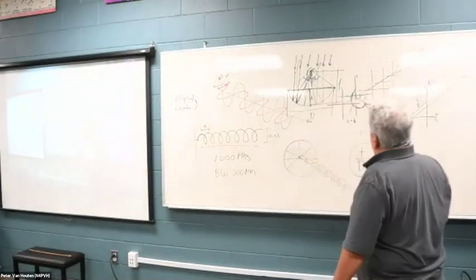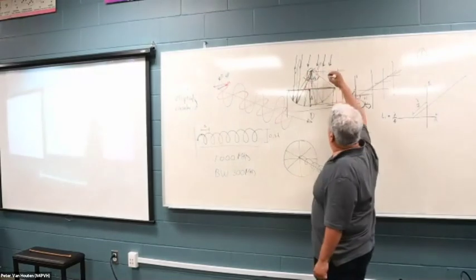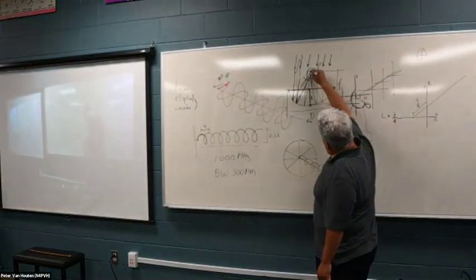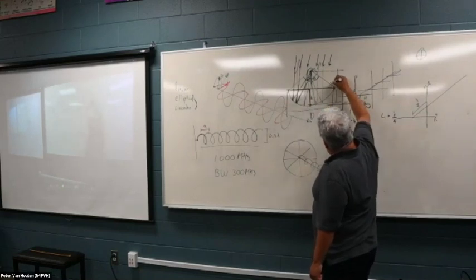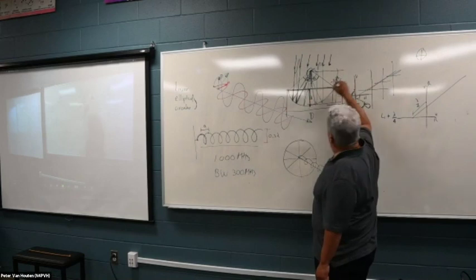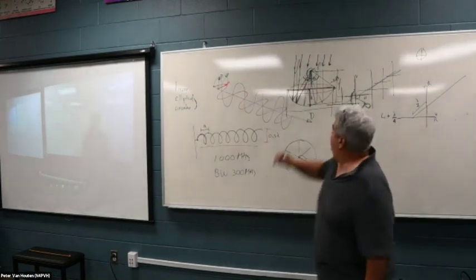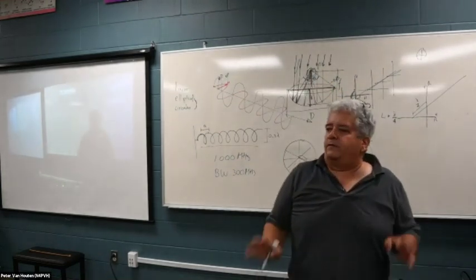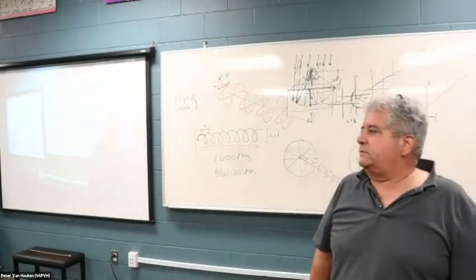So you have to put an antenna here that has a pattern such that the gain, of course, in the center is going to be the maximum, but at the edge should be around 10 dB less. So whatever you get here, your edge should be receiving 10 dB less from this antenna. That's the optimal illumination for a parabolic antenna.